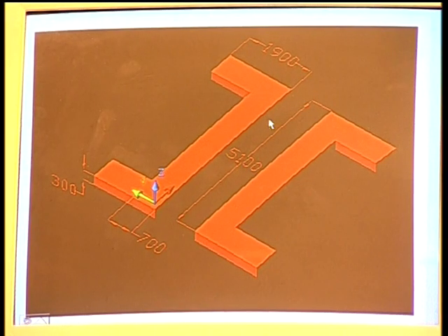Now, before starting the detailed estimation, let us see a three-dimensional construction sequence of RCC slab culvert. Let us look at the picture. Now, here you can see the foundation. The foundation consists of a channel shape. So, this web portion is the abutment portion, and this is called a return or wing wall. This return is 90 degrees, that is perpendicular to the abutment. So, when it is perpendicular to the abutment, we call it a return. We can also call this a wing wall.